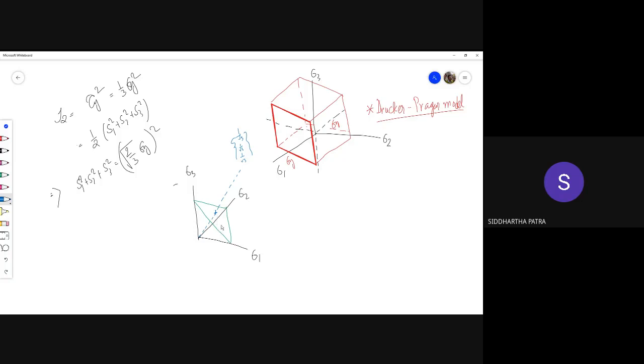Any stress state sigma, in the principal coordinates, is a sum of the hydrostatic part, which is basically minus p times I equals sigma m times I, where sigma m is the trace of sigma by 3, the hydrostatic part essentially. And then there is your